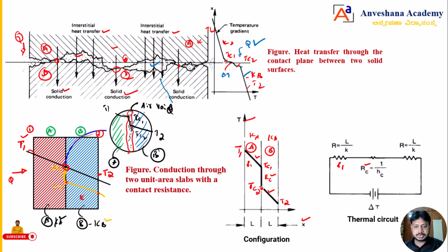Next, heat is going to transfer from this intermediate point to this point. That means temperature again decreases, linearly. But when the heat moves from this point to this point, there is some resistance, which I will mark here as R2. So R1 represents the resistance of material 1, Rc represents the resistance due to thermal contact, due to contact of the materials, and R2 represents the thermal resistance of material 2. These three are in series, dear students.